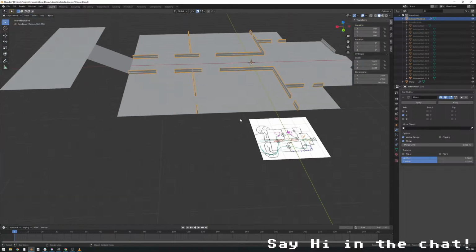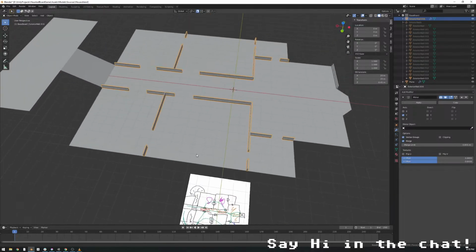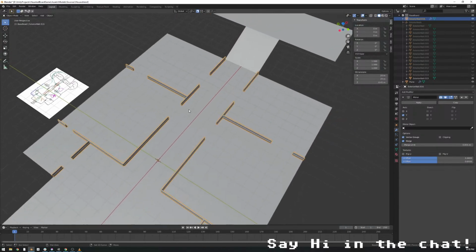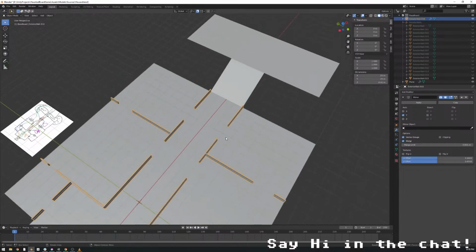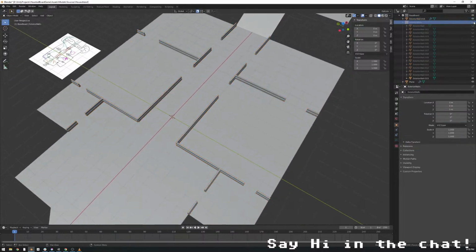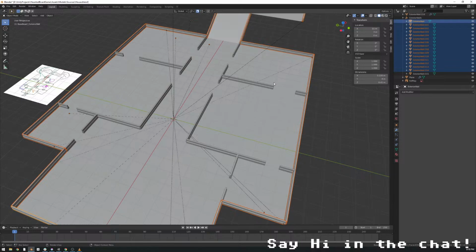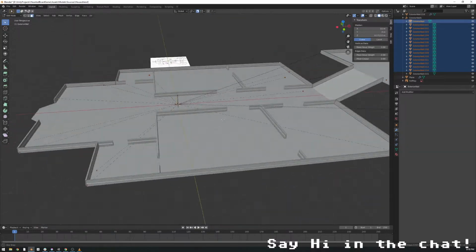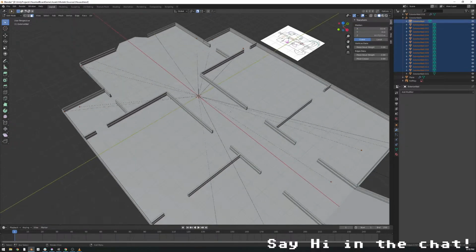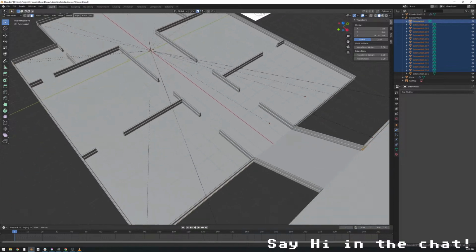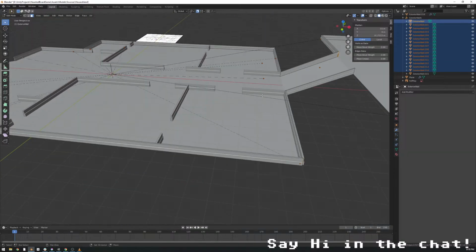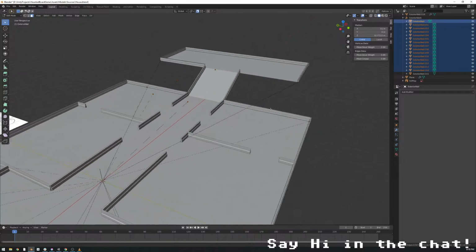There we go. Got some interior walls going. So now we can move around this space. And we're still on a grid. We've got our exterior walls. We've got our upstairs room. Let's unhide all of these. That's not the way to do it. Alt H, unhide. Okay. Lesson learned. You know, just extrude them out and don't worry about snapping everything around.